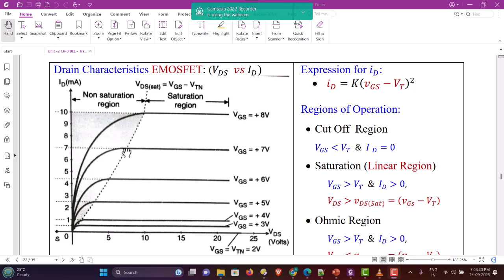If the voltage VDS is greater than this value, say around 7 to 8 volt onward, the channel will be tapered and the limited number of charge carriers passing through the shrunk area near the drain are constant, and therefore the drain current saturates and remains constant.